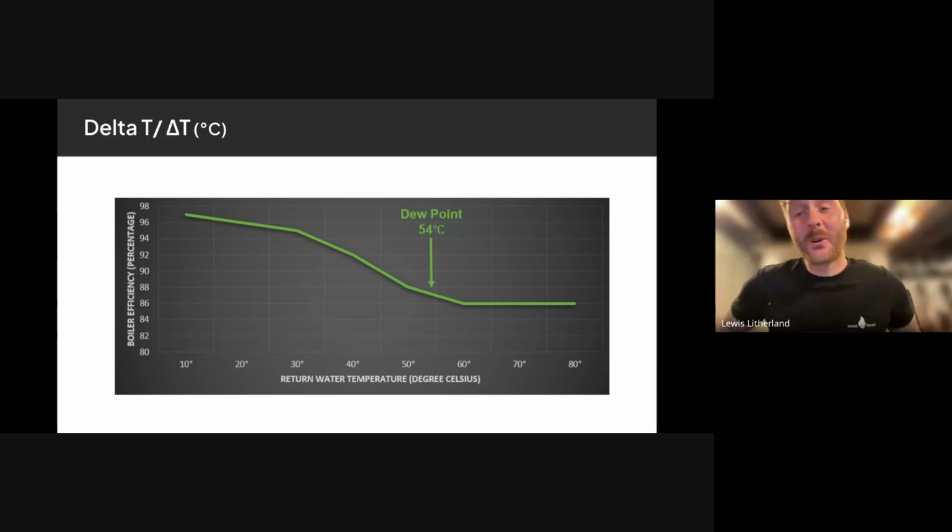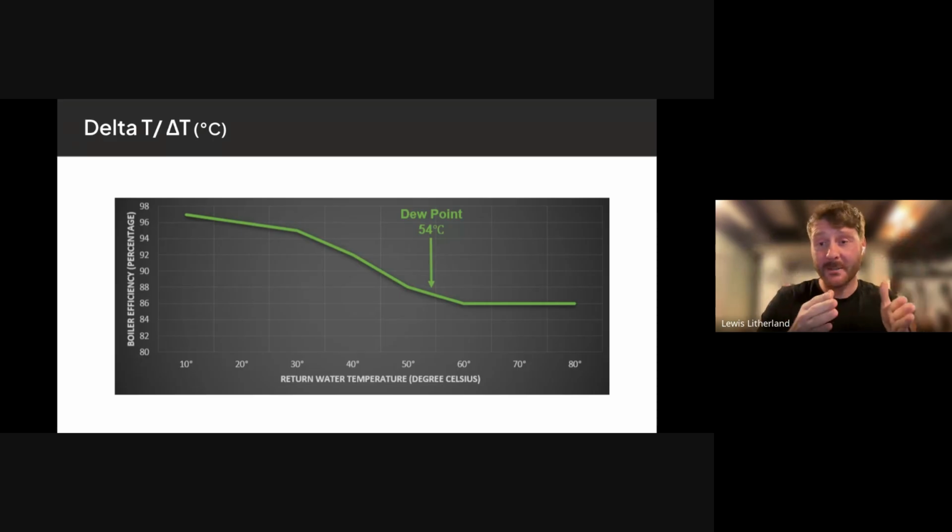You can go as low as your boiler will take you. There is a Brilliant slide on this, and I like that you've asked that, because once you get into this, you suddenly become like a snob with boilers. You think, that boiler's a lot better than that boiler because it can do this. But yeah, the lower you can go, the better.